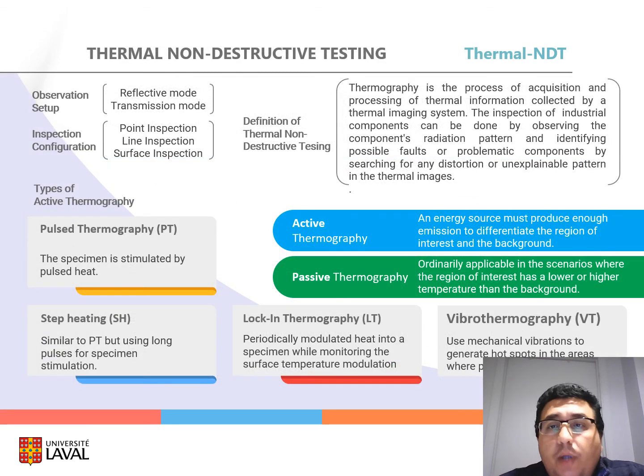Thermography is the process of acquisition and processing of thermal information collected by a thermal imaging system. The inspection of industrial components can be done by observing the component's radiation pattern and identifying possible faults and problematic components by searching for any distortion or any unexplainable abnormality in the thermal image.